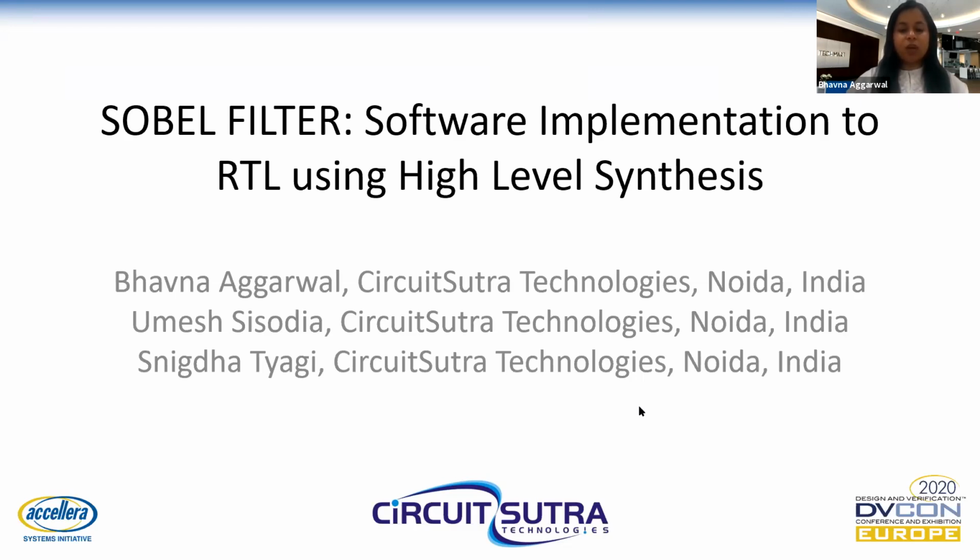VHDL. For our research, we chose a widely popular software algorithm known as SOBEL filter and generated a functionally correct RTL through it in the form of Verilog. Technically, we will discuss the efforts in migrating an open source image processing algorithm to a synthesizable C design using the HLS Synthesizable library and an HLS tool from Mentor called Catapult.